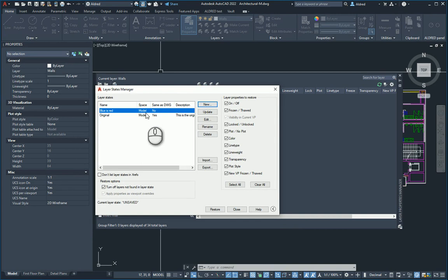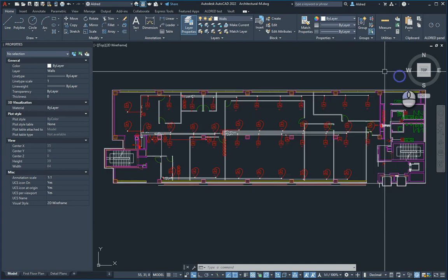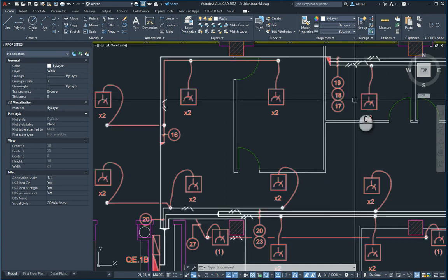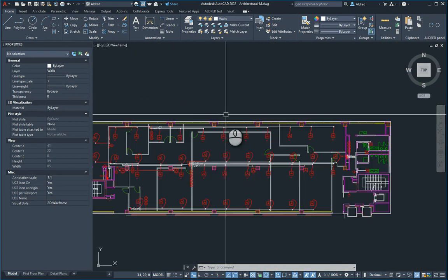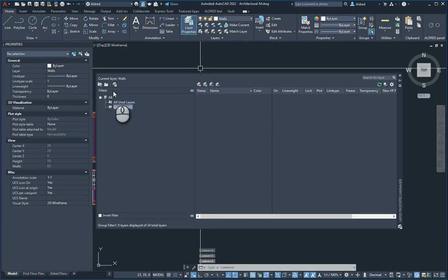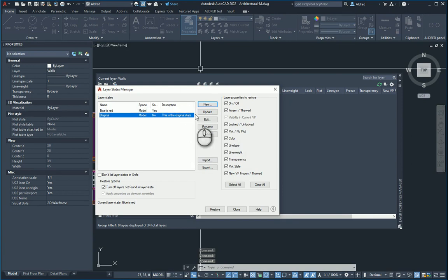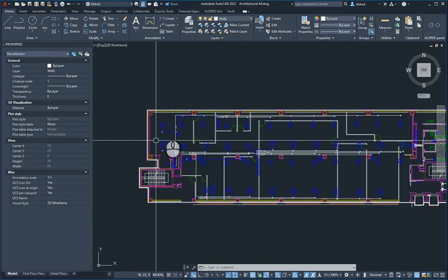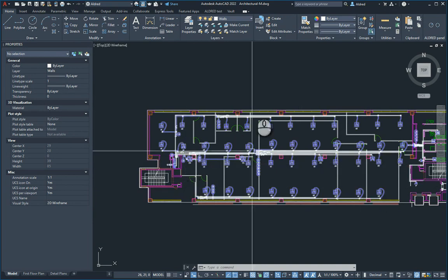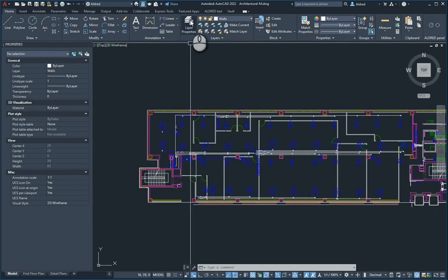No, it's not. It's telling me that in the current DWG at the moment, blue is actually blue and it's not red. So what I'm going to do is restore that layer state, and there you'll see everything has now become red. All of this was blue previously. Now if you want to go back to the blue, let's go the normal way over here. Layer states, we'll say the original, and restore, go back, and there we can see it's all blue again.